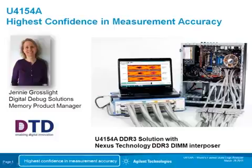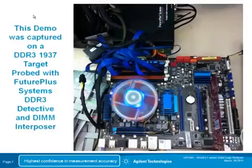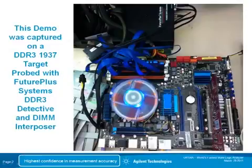Hello, I'm Jenny Grosslight, here to introduce Agilent's new U4154A 4 gigabit per second state mode logic analyzer, capable of capturing signals with data valid windows as small as 100 picoseconds by 100 millivolts at the probe point, providing you the highest confidence in measurement accuracy. Our target for this demonstration is a DDR3 desktop operating just under 2 gigabits per second.